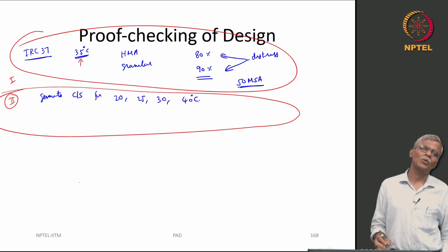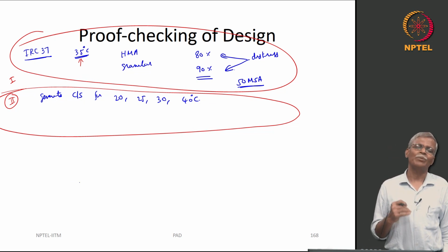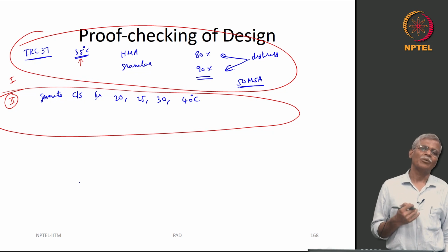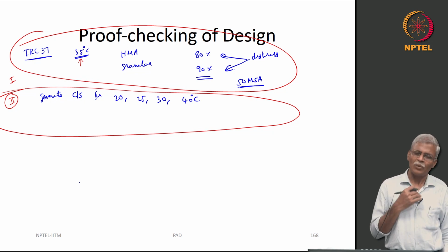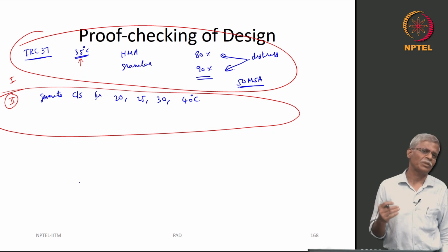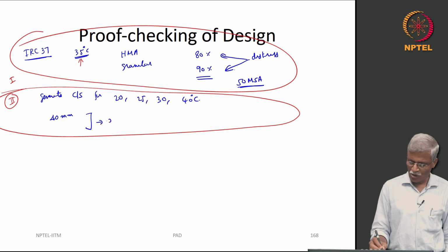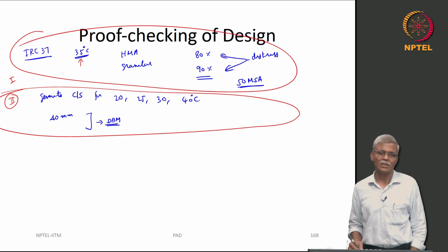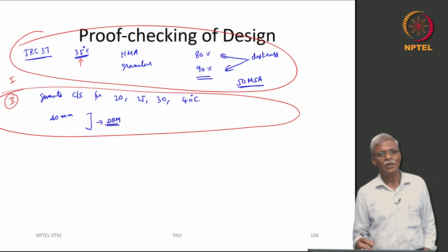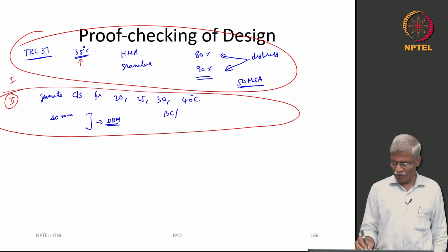So, you can still say that, okay, let me do the following, I will keep the foundation, that is my thickness of base and sub base, the same, and I will only play around with the bituminous layer. In fact, you can even take the attitude saying that, okay, I am going to keep 40 mm for BC everywhere, and I am going to only change the DBM. Or you can do the following, since there is so much variability there, you can play around between BC and DBM thickness for different binders.